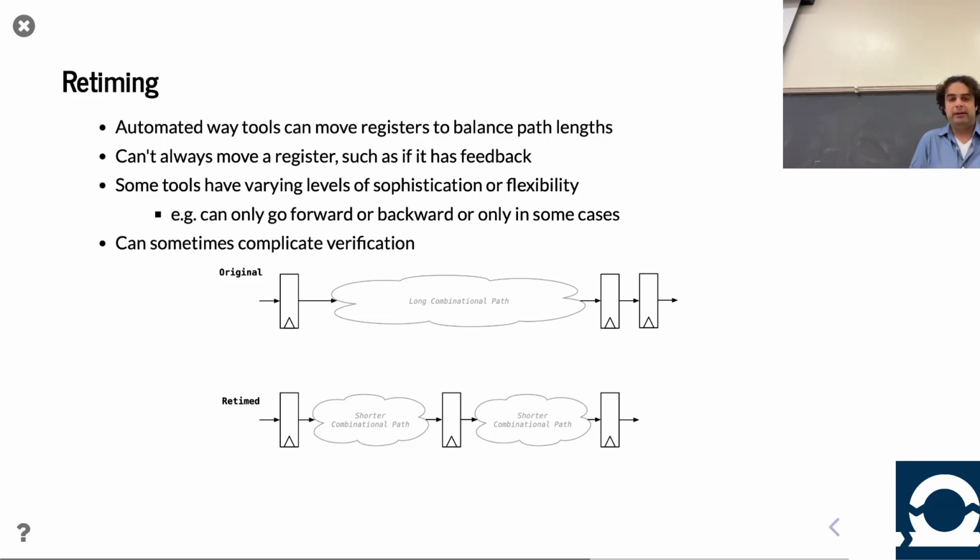You can use logical equivalence checking, or LEC, to figure out how to transform the values in the registers when you're verifying to make sure it matches what it should have been. In other words, you move registers around, you change what these registers represent, but there is a logical transformation to get from what you have to what it should be, and you can still do verification with it. So retiming is really, really important.